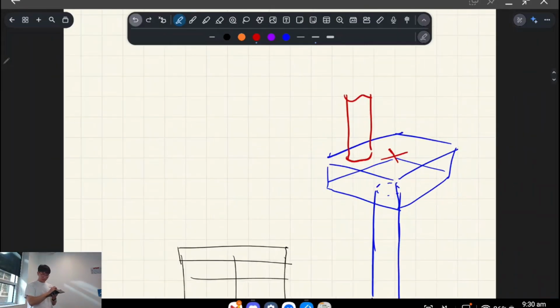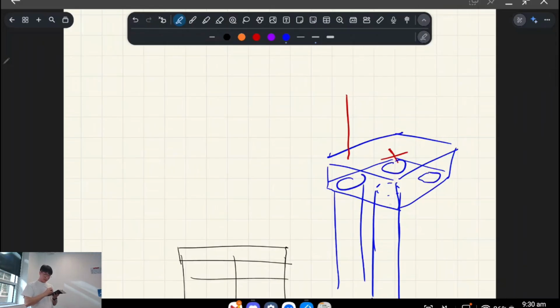Another reason you might want a pile cap is if you have multiple piles and you want to combine their strength. Say the force does land directly in the middle. You've basically engaged 4 piles through one really, really heavy column, if that makes sense.